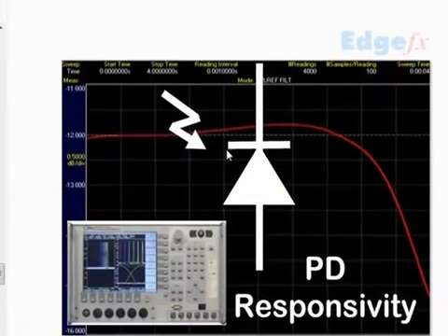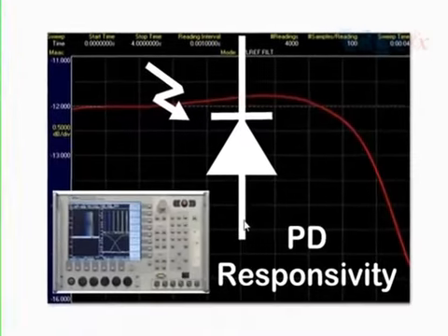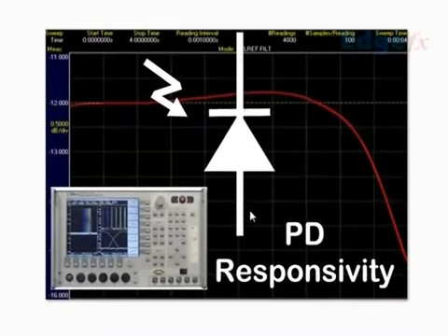Actually, the peculiarity of this diode is that when light falls on this, it starts conducting in this direction also, only when the light falls on it. So in a multimeter, in a diode test, it will not show from here to here, not here to here, but you have to follow certain tricks to test this photodiode.